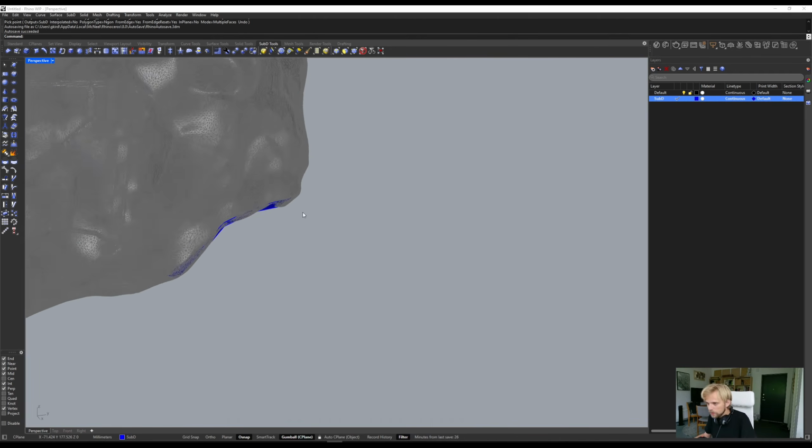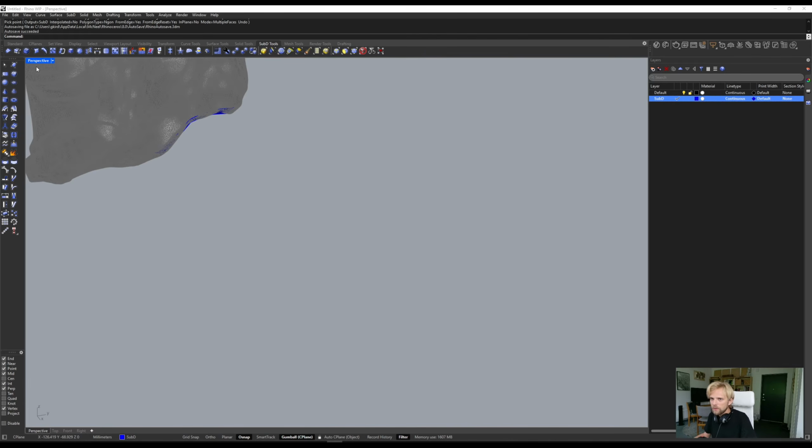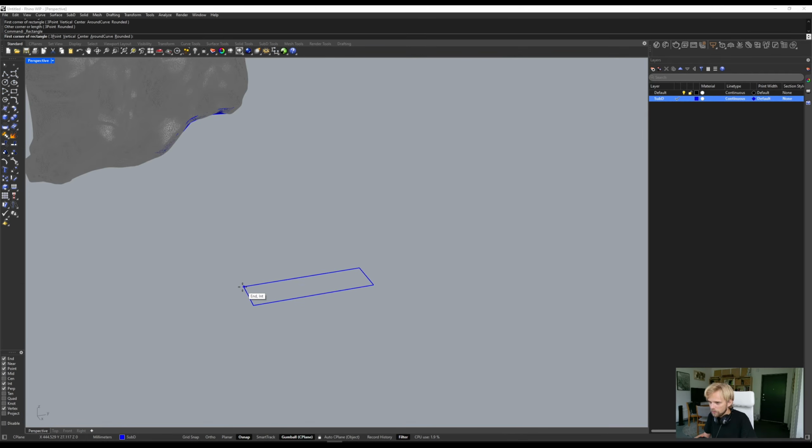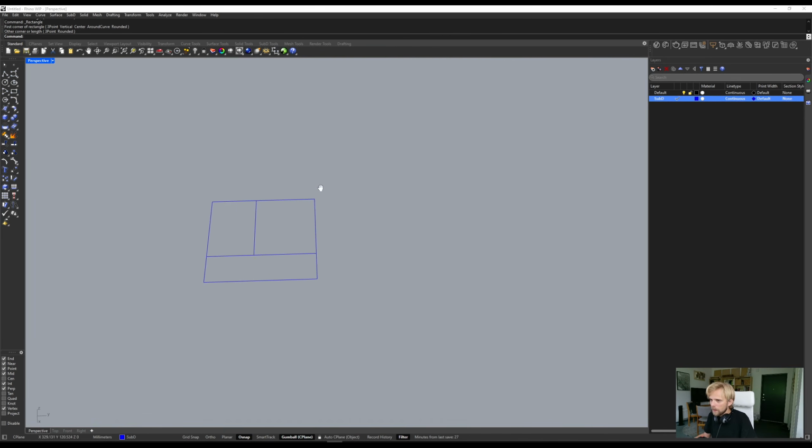Too many polygons. Another rule for sub-D creation is that you can never ever, this is important by the way, or you should never, have sub-D faces doing something like this. This point right here would be super problematic, and it would actually be registered as a hole inside of the sub-D, right?